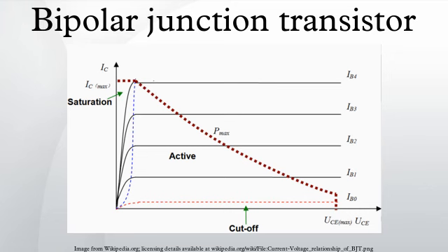Temperature sensors: because of the known temperature and current dependence of the forward-biased base-emitter junction voltage, the BJT can be used to measure temperature by subtracting two voltages at two different bias currents in a known ratio. Logarithmic converters: because base-emitter voltage varies as the log of the base-emitter and collector-emitter currents, a BJT can also be used to compute logarithms and anti-logarithms. A diode can also perform these nonlinear functions, but the transistor provides more circuit flexibility.